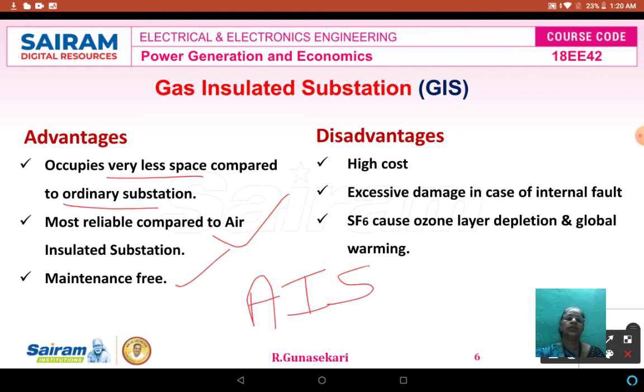What are the disadvantages? High cost, because SF6 gas is used, so the cost is high. Then excessive damage in case of internal fault, which is another disadvantage. Then, since we are using SF6 gas, it causes ozone layer depletion and global warming, so this is also a disadvantage of the gas insulated substation.